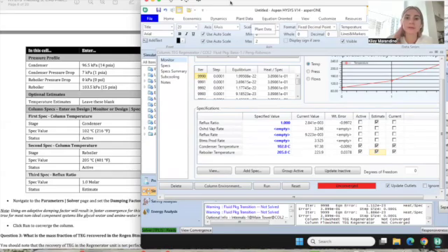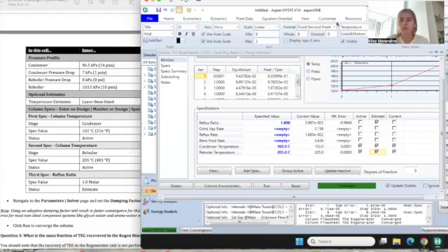Unconverged. Let's see what's going on. If you have that error where it unconverges, it's possibly just because this calculated before we were able to specify our value. So if that happens to you, but your screen looks just like this, just hit the run button again and it will converge.